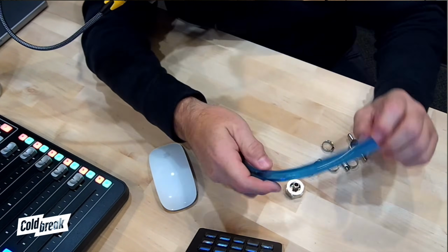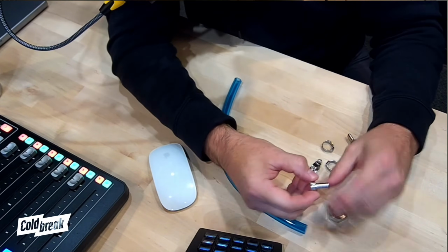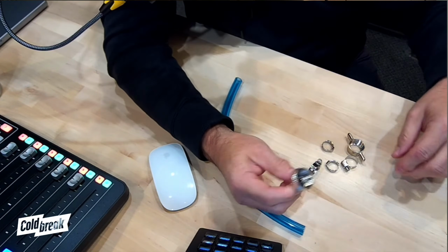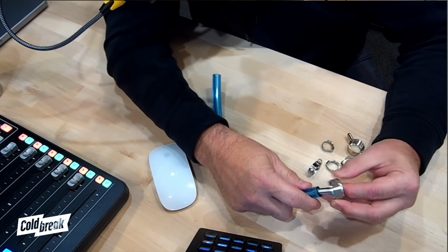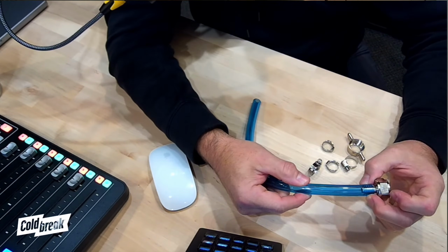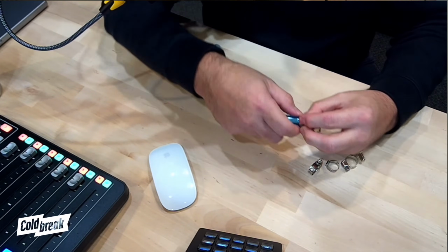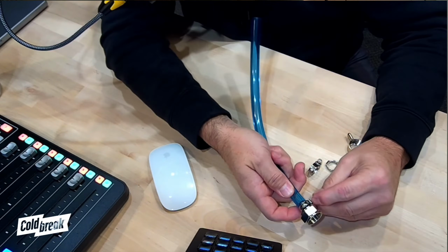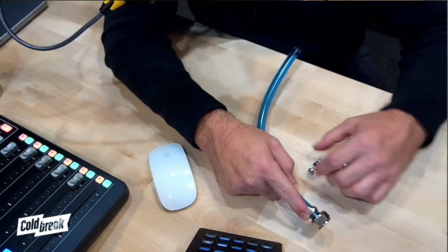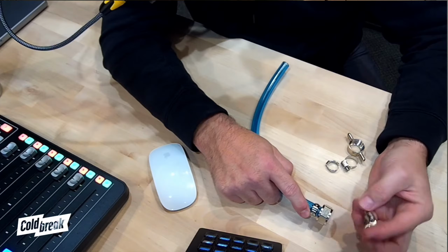So I do have a piece of vinyl tubing here. Here we have our tailpiece. We have our beer nut, or our hex nut, which then pushes onto your tubing. And then in order to attach that tubing to the tailpiece, you're either going to use an Oetiker clamp, which is like a stepless clamp, which you need a special tool to pinch, and is more of a permanent installation. Or you can use a worm clamp, which can be tightened and loosened with a screwdriver.